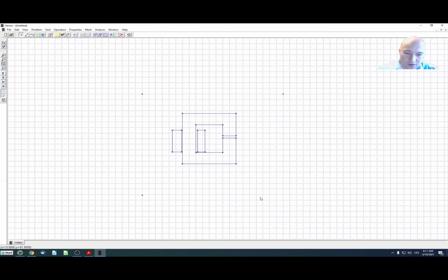The width of your boundary actually depends on the shape of your magnetic core that you're solving and on the magnetic flux. But if you make it larger, it will have an impact on the calculation time.